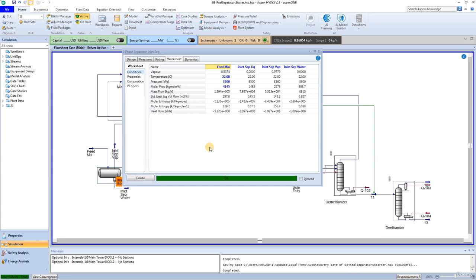First, the program calculates the initial phase dispersion based on the feed flow through an inlet nozzle. All 3 models assume the inlet dispersion follows a Rosin-Rammler distribution. After this inlet dispersion is calculated, the program calculates the carryover after the primary separation of each phase in every other phase.